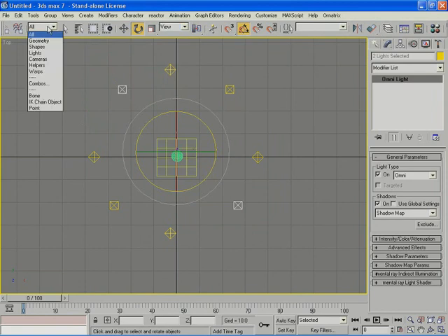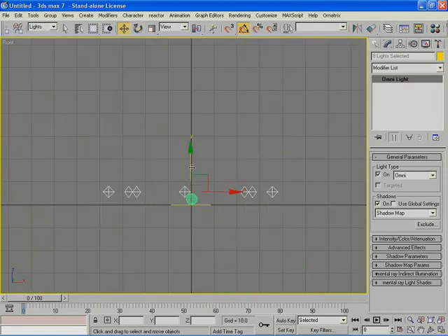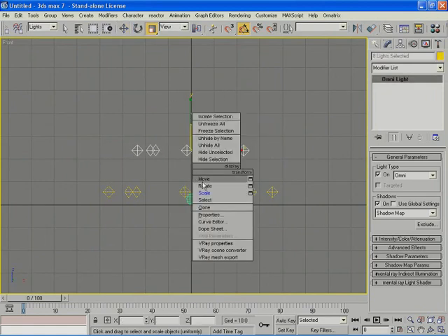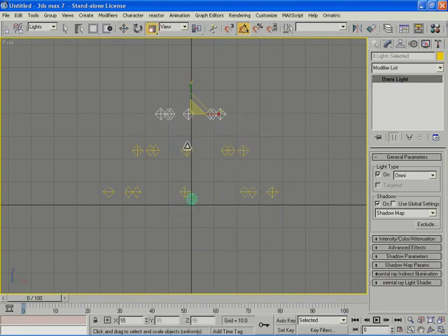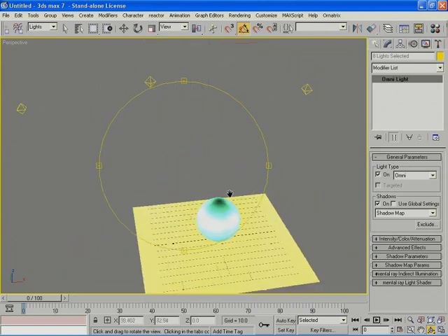The reason I'm modeling this light rig into a dome is that I'm trying to simulate a skylight environment because the Earth is spherical and therefore the atmosphere around the Earth is also spherical. Therefore, any simulation of that light should also be spherical to get a realistic result. So this used to be the old way of simulating global lighting. So here, of course, the light is very strong around the object, so I'm going to go to intensity and tone down the intensity. And everything will be toned down because of the instance.